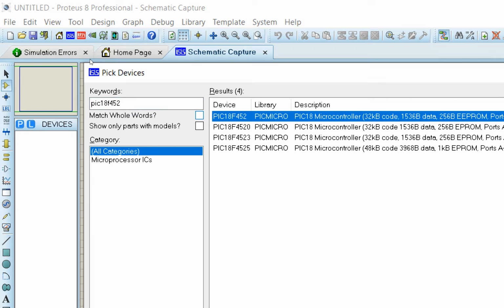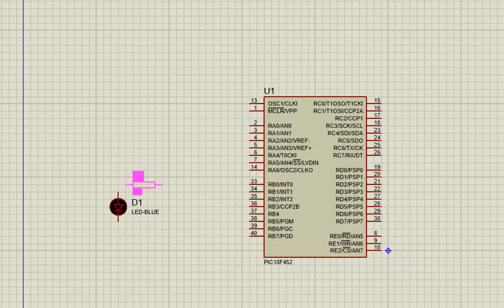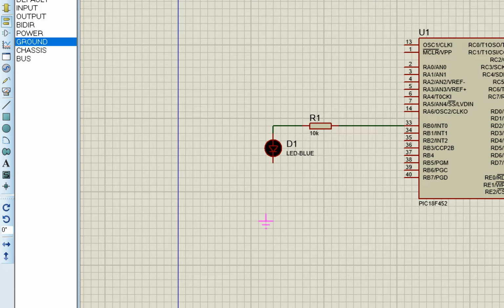Go back, take an LED, whatever LED you prefer. I'm gonna use a 5mm blue LED. Okay, this is the blue LED. So place it anywhere you prefer. I place it here. Now we need a 220 ohm resistor. In the simulation, it is not necessary, but in case of actual hardware, you will need a resistor to limit the current. Now connect them. It goes here, here, and then we ground the LED. Use the virtual ground like this, and you click on here to ground it.